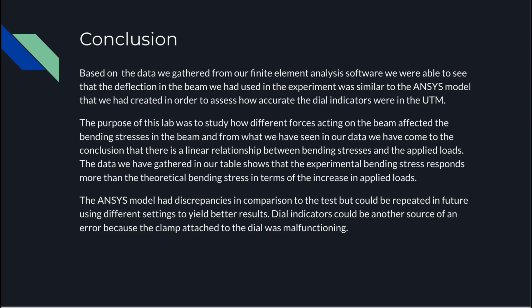The purpose of this lab was to assess different acting forces on the beam and how they affected the bending stresses in the beam, and from what we have seen in our data, we have come to the conclusion that there is a linear relationship between bending stresses and the applied loads. The data we have gathered in our table shows that the experimental bending stress responds more than the theoretical bending stress in terms of the increase in applied loads.